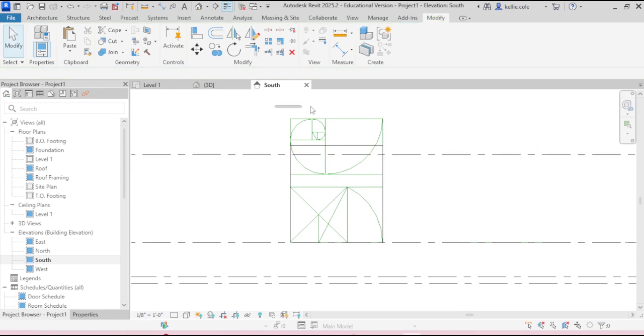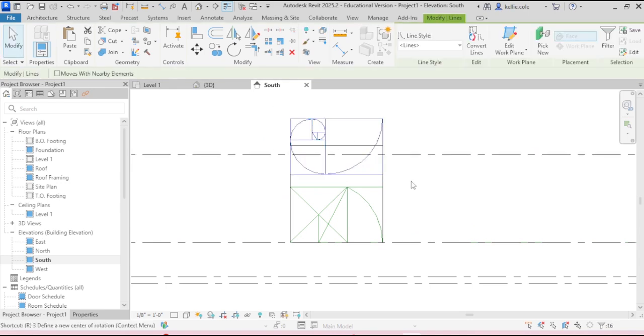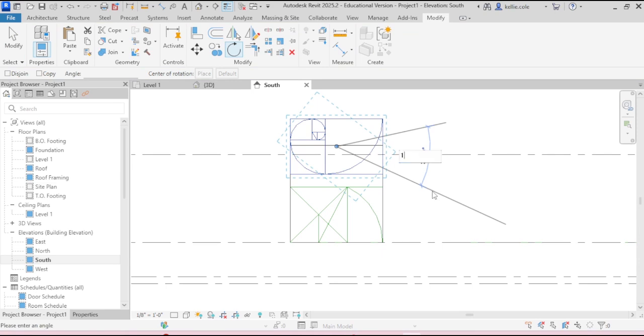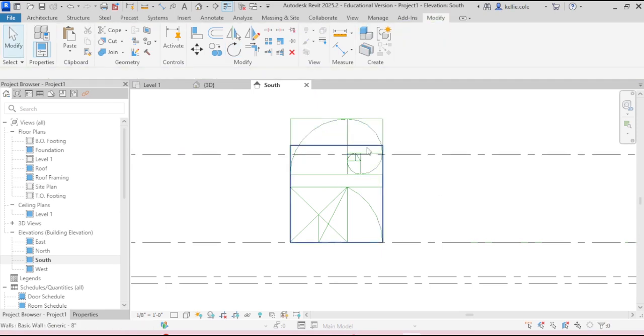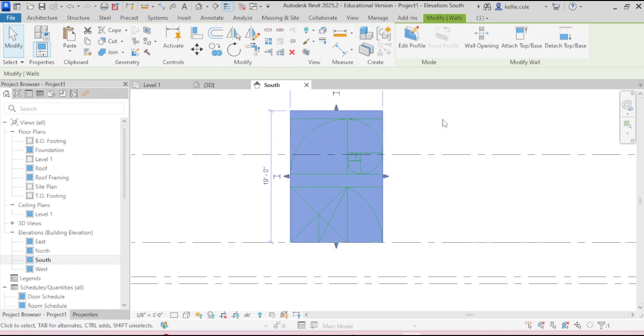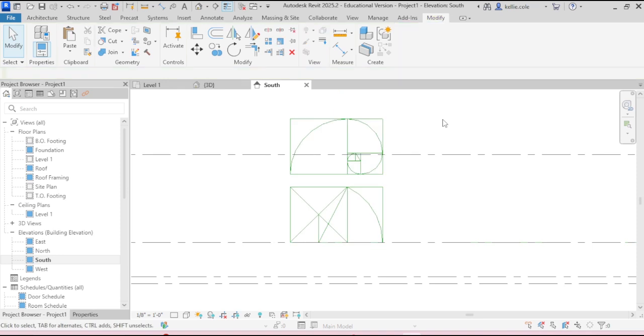It uses our same plane, and I'm going to rotate this, allowing the rotation tool to align it in the center. We can hide elements in drawings and find them again. So if the wall is disturbing you in this view for any reason, click the wall and touch Element Hide, which is EH. You can also get to that by right-clicking your mouse.